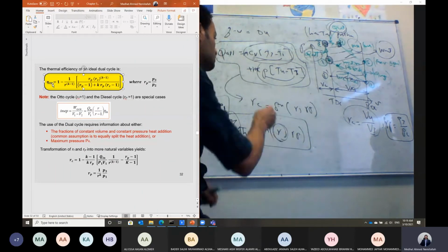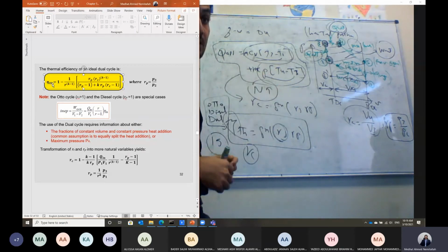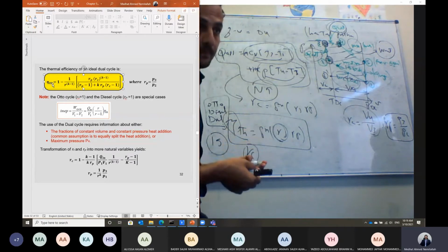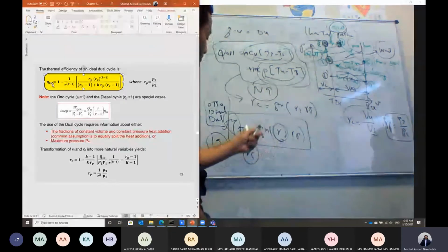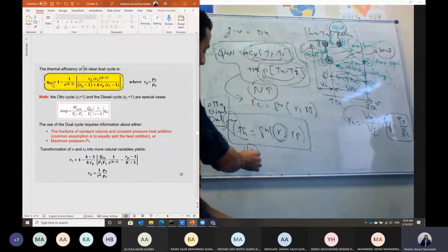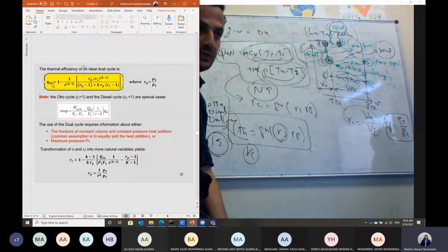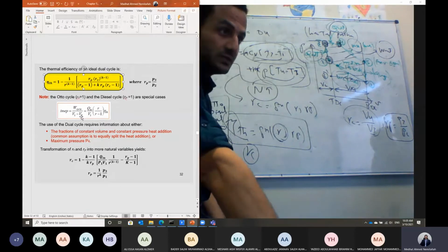That's why we cannot actually go for a diesel engine with higher RPM. And also the diesel fuel is a heavy fuel, and it results in additional emissions in terms of soot and particulate matter. And also due to the higher compression ratio, usually the diesel engine is a noisy engine, and it is a heavy engine in this case. But it is efficient. As we said, in all cases, it is an efficient engine.